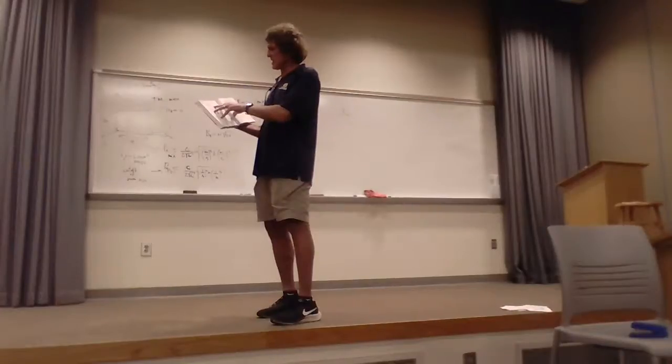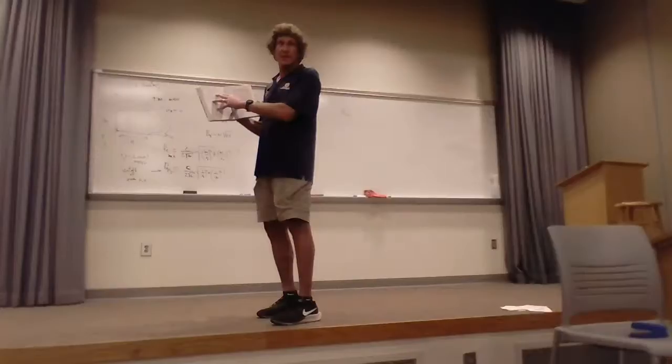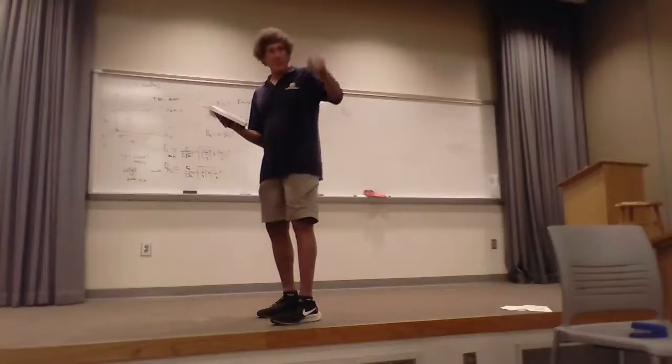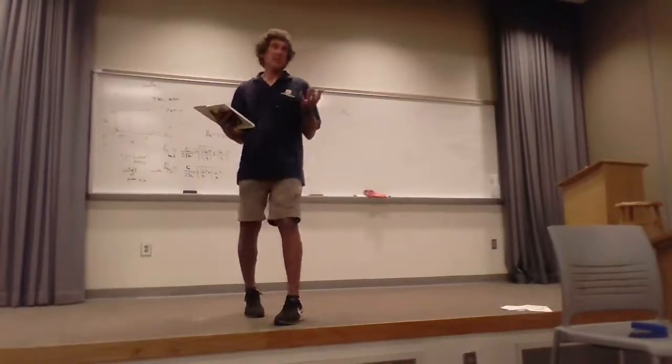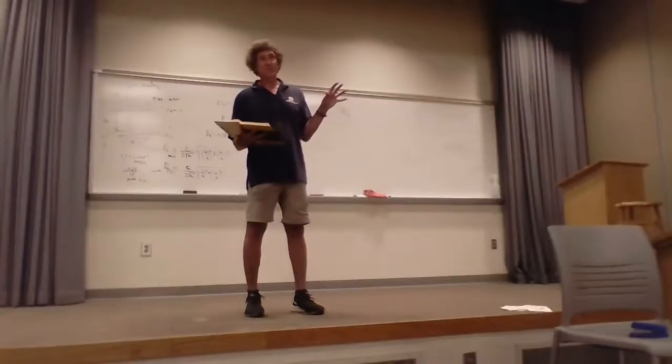If you look at EZ, you see how it's a half wavelength from across. Do you have your book or? It's a half wavelength. Well, if it was a 2-0 mode, or I mean a 2-1 mode, then you would have a full wavelength. You would see 2 humps there. And it's called the field mapping, where the way the field is arranged that will allow propagation.